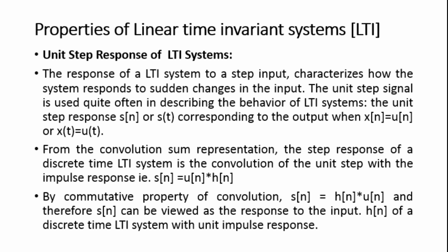Next is the unit step response of an LTI system. The response of an LTI system to a step input characterizes how the system responds to sudden changes in the input. The unit step signal is used quite often in describing the behavior of LTI systems. The unit step response s[n] or s(t) corresponds to the output when x[n] is equal to u[n] or x(t) is equal to u(t).